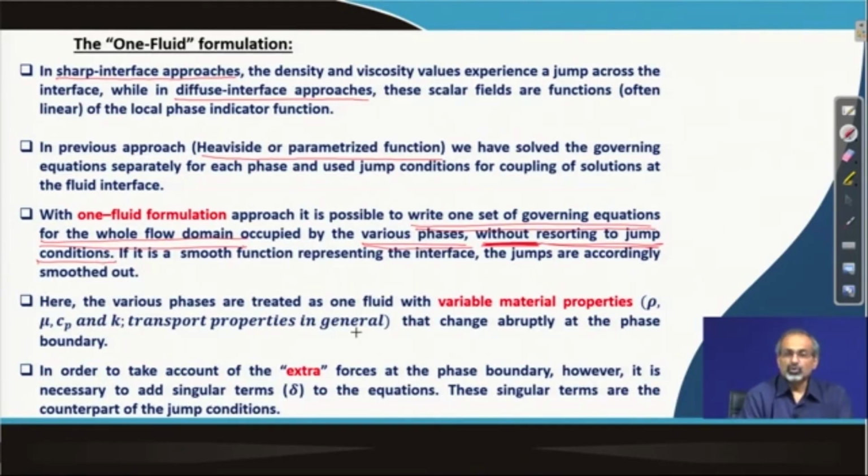Of course, if you do not do that, you have to tackle the variation across the interface in some other alternative manner, and that alternative manner in this case would be introduction of some kind of a source term, which gives you an analogous effect in the form of a kind of forcing, which explains where the interface is. That means, in spatial sense, at a specific time instant, if in some regions of the flow we find that the forcing terms are becoming active, then those are the regions which form a part of the interface.